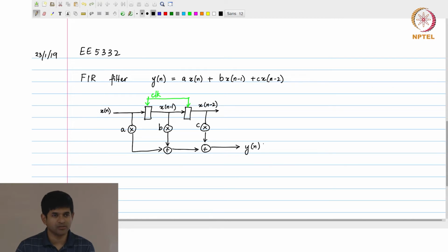And what determines that? What would it be that determines the rate at which this architecture can process data, assuming that somehow I can provide my input samples fast enough? Remember, we had this discussion earlier where we said that normal signal processing algorithms very often have their sampling rates set by some physical constraints. For example, there's no point in sampling voice, or even music, at more than, let's say, 44 kilohertz, because the human ear cannot really sense anything beyond that. Similarly, for vision, more than 60 frames per second is unnecessary because you really can't make out that level of detail. In fact, 30 frames per second is the limit of persistence of vision. So there are physical reasons why certain signal processing applications have a required sampling rate.